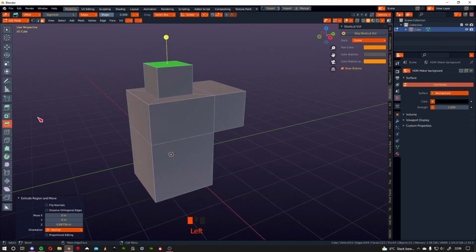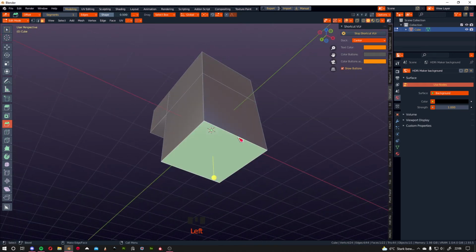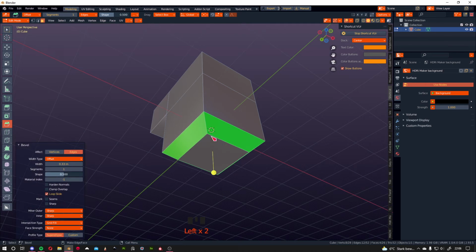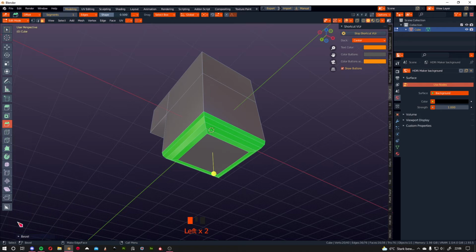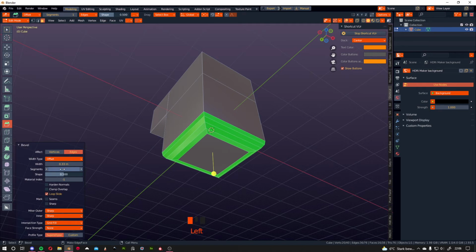Now the bevel tool. The bevel tool is made for beveling edges. When I'm dragging this, instead of moving the face out, I'm moving the edges down. That creates a beveled edge. I basically chamfer the edges, and I can say how many segments I want. If this is not on top, you see it down in the corner: you can click on bevel and then you get your bevel segments. You can play around with this.